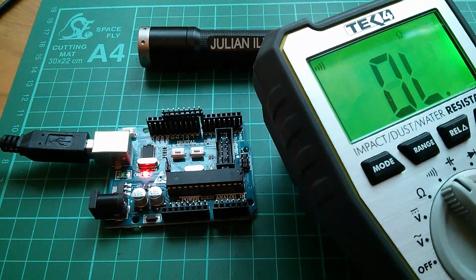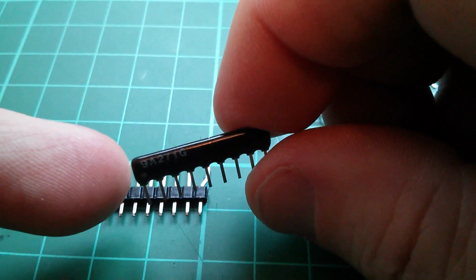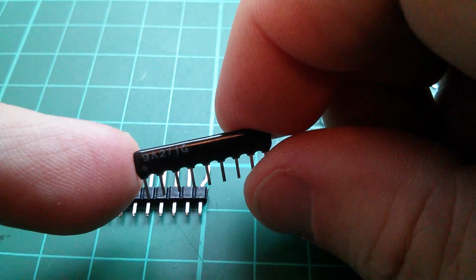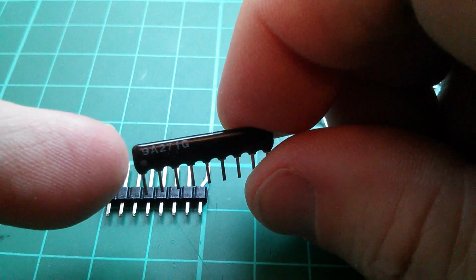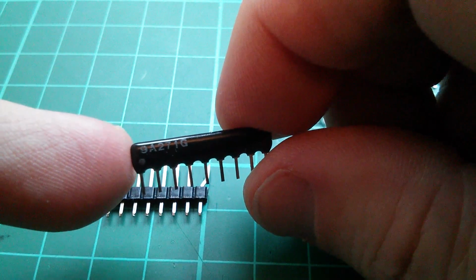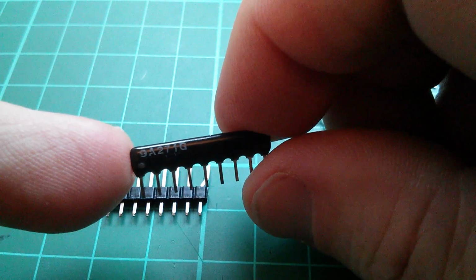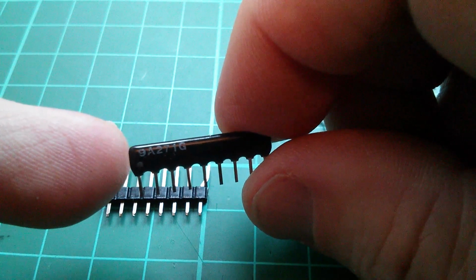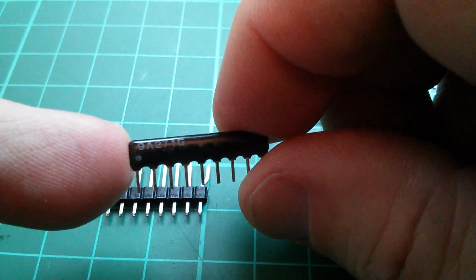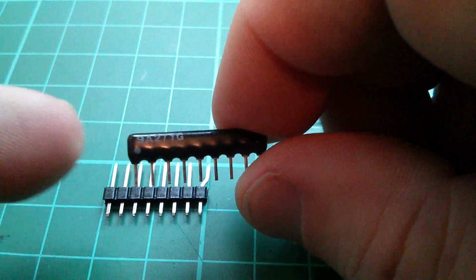Yep, that seems fine. Now I'm using a 270 ohm single inline resistor pack here. No particular reason for the value, it's the highest value resistor pack I could find, but anything between about 220 ohms and, oh, I don't know, 1k probably would do. This is going to mean I'll have quite bright LEDs.